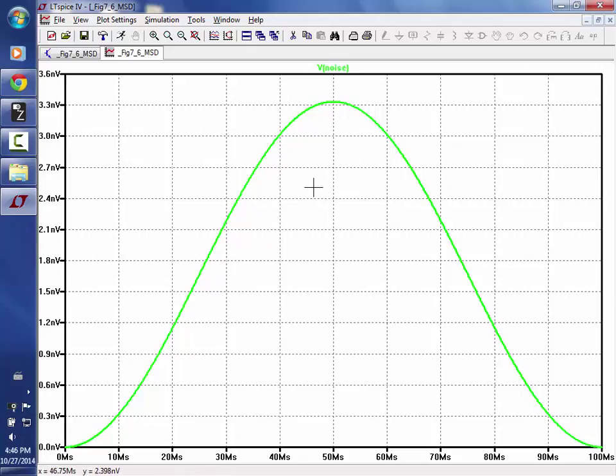So I pass this spectrum through a low pass filter. So if I had a sinusoid at 2 megahertz, this is my input signal, how would I modify this? This is my spectrum of my modulation noise. If I have an input sine wave at 2 megahertz, tell me how to show that in the spectrum. Yeah, an impulse right here at 2 megahertz sticking up, right? Boom, there it is.